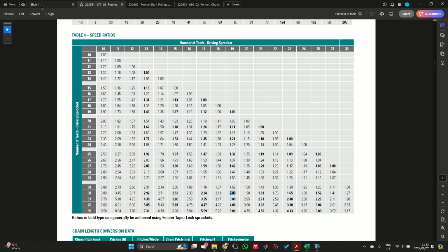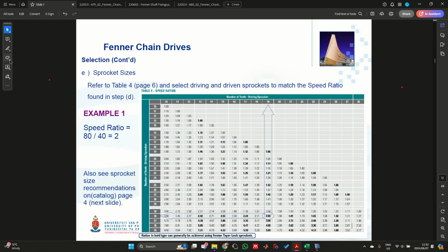Okay, so to do that, what we can use is the gear ratios that we have available. To illustrate that, if I have omega 2 over omega 1, so the RPM of shaft 2 divided by the RPM of shaft 1, then this will be set equal to N1 over N2. This is a standard equation that we have available.